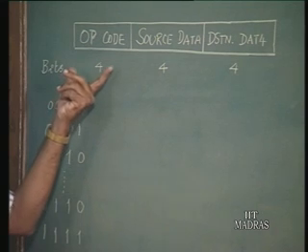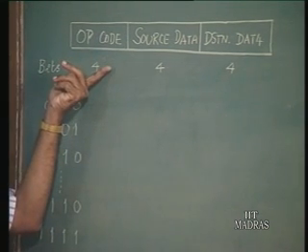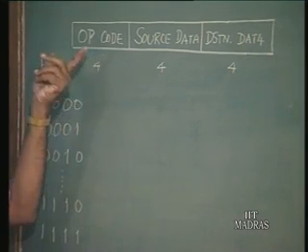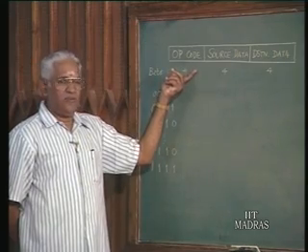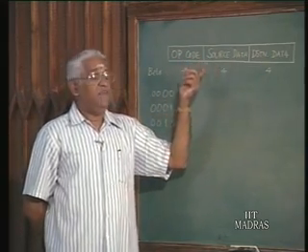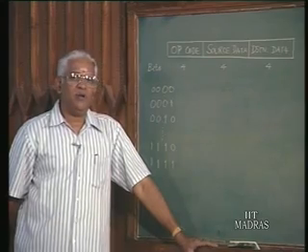While discussing these 4 bits, we said 2 to the power 4, that is 16 combinations, are possible, that is 16 opcodes. With this opcode field, we must identify whether we are referring to no operand, single operand or double operand instructions.